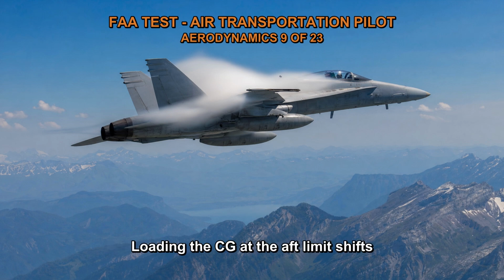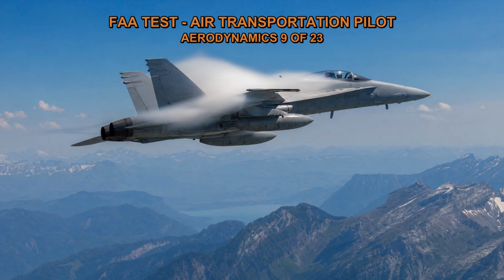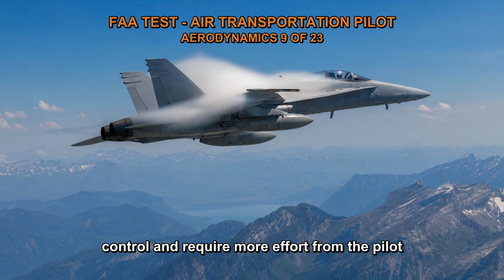Loading the CG at the aft limit shifts the weight distribution towards the tail, making the tail heavy. As a result, the nose-down pitching moment increases, and the aircraft can feel less stable in pitch. This can make the aircraft more challenging to control and require more effort from the pilot to maintain the desired pitch attitude.